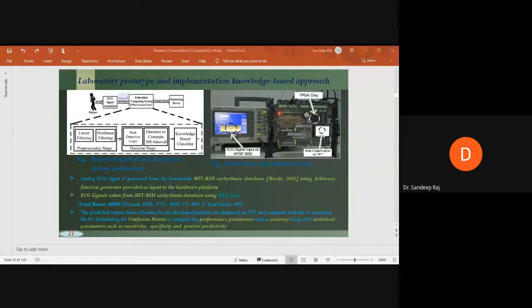This requires 4n/2 complex multiplications for the full filters. And finally, 2 blocks are added and 2 inverse FFTs are applied. In comparison to the classical DWT, meaning the conventional discrete wavelet transform, which is implemented by cascading high pass and low pass filters, the comparison is evidently in favor of the FFT version of the DWT, because as the signal length increases beyond 16, we find that the execution time of the algorithm is very less.